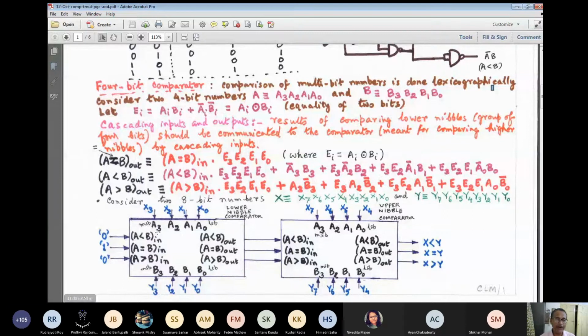It means that so far, we have started our comparison from the lowermost end. We have seen so far that A and B are two numbers which we are comparing. So for example, we are in the first nibble, A0 to A3, B0 to B3, then the second significant nibble, A4 to A7, B4 to B7. And now suppose on this particular 4-bit operand I have inputted x8, x9, x10, x11, here y8, y9, y10, y11. Good. So what will be conveyed through these three cascading inputs?